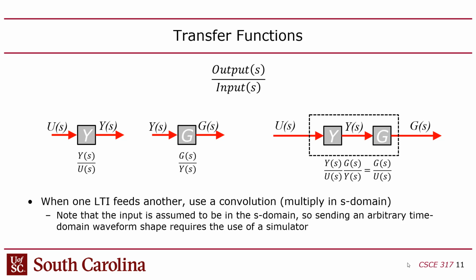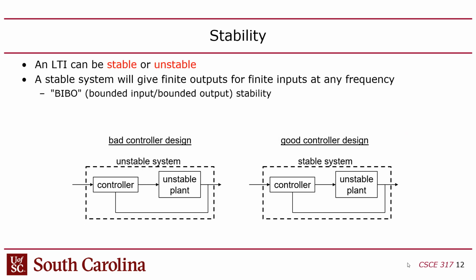Well, the point is that you want to check to see if that whole system is stable. You want to hit it with an impulse response to see if it's inherently unstable. You want to know if it has bounded input, bounded output stability, meaning if you give it a bounded input signal, hopefully it has a bounded output. That still doesn't mean it's a good controller, but that's the baseline you have to achieve. You don't want any control system that is unstable. The plant by itself could be unstable, but together, the combination of the two should make a stable system.